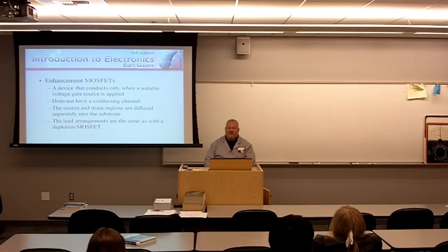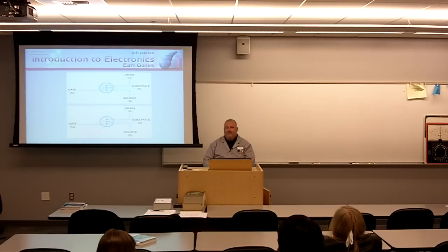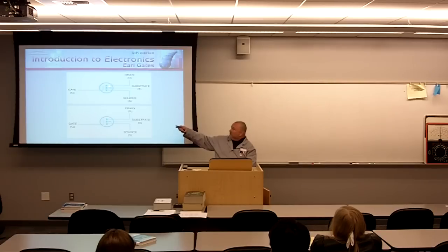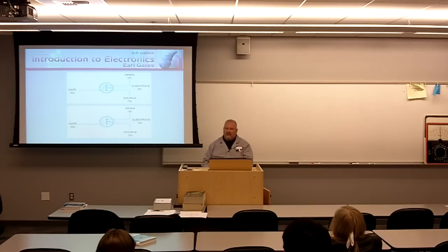The lead arrangements are the same as with a depletion MOSFET. See, here there's no channel, and that's on a schematic diagram how they're going to make it look. So now we've got to influence this with a voltage in order to get current to flow, source to drain, and to be able to gate that. And these are even more efficient.